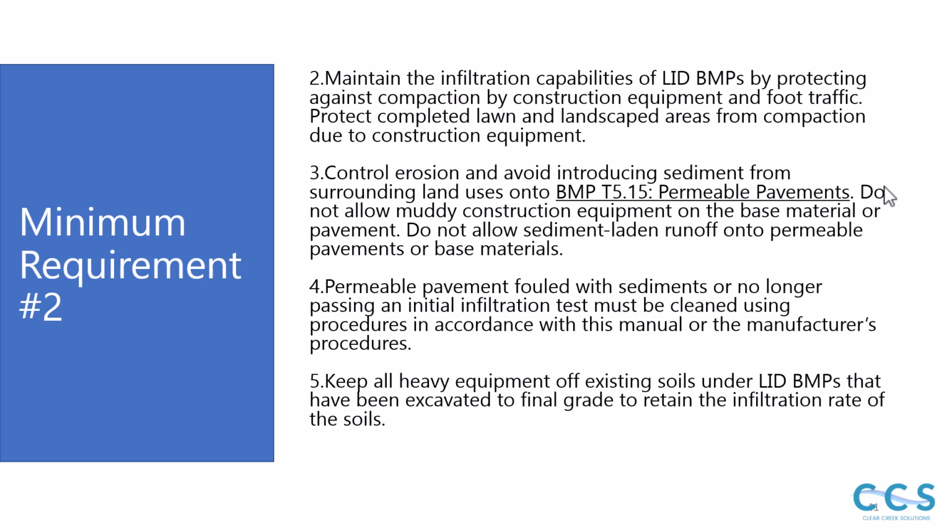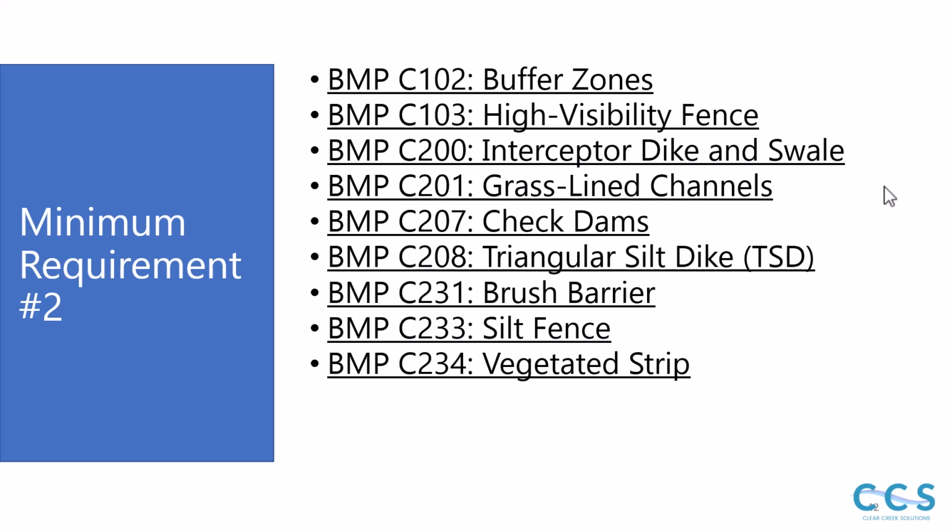Permeable pavement fouled with sediments or no longer passing an initial infiltration test must be cleaned, and keep all heavy equipment off existing soils under LID BMPs that have been excavated to final grade to retain the infiltration rate of the soils. And then we have 9 BMPs applicable there. So that is covering minimum requirement 2.